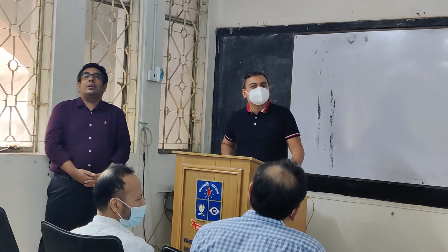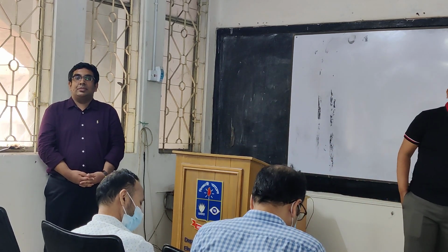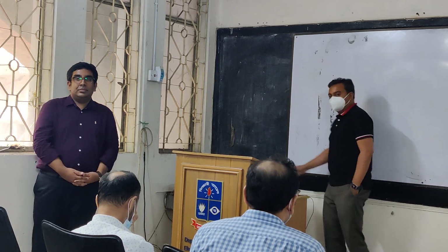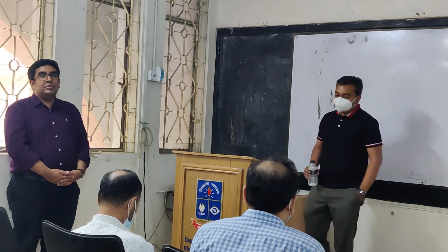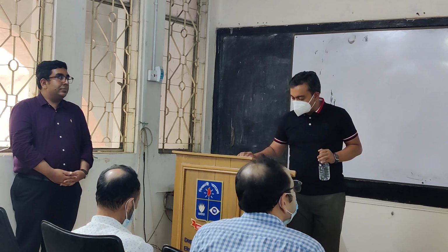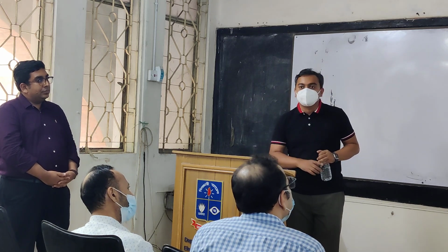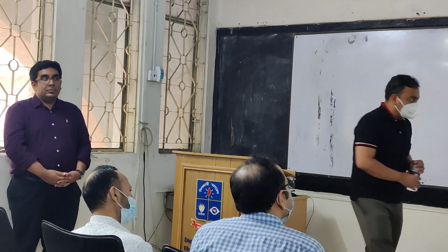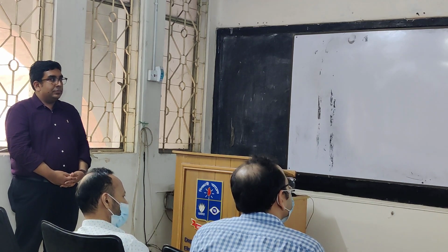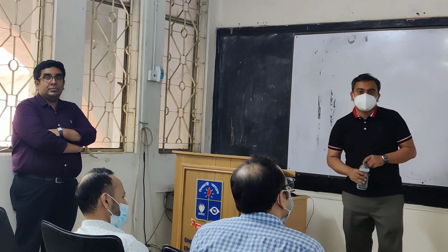Sir, I have several questions. Go ahead. So, first of all, what is the switching performance of such a transistor? What does that mean? Like how fast it can go from on to off state? So, you see, I did not spend too much time, but this particular data is up to 20 gigahertz. We have other results, if you look at this paper, up to 40 gigahertz. So you can say that up to 2.5 picoseconds, it looks fine.